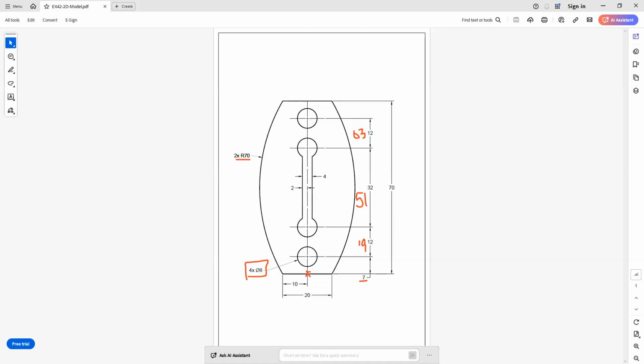Now, remember with the arc, always think counterclockwise. And what I mean by that is that anytime you're creating them, AutoCAD creates things in a counterclockwise rotation, right? So this means positive. If you're ever thinking about anything to do with rotation, counterclockwise is positive. So when I'm creating these arcs, this bottom part is where I would start this arc because I want to go in a counterclockwise rotation. So I'm going to go up this direction. My starting point will be here, and then my ending point would be here, right?